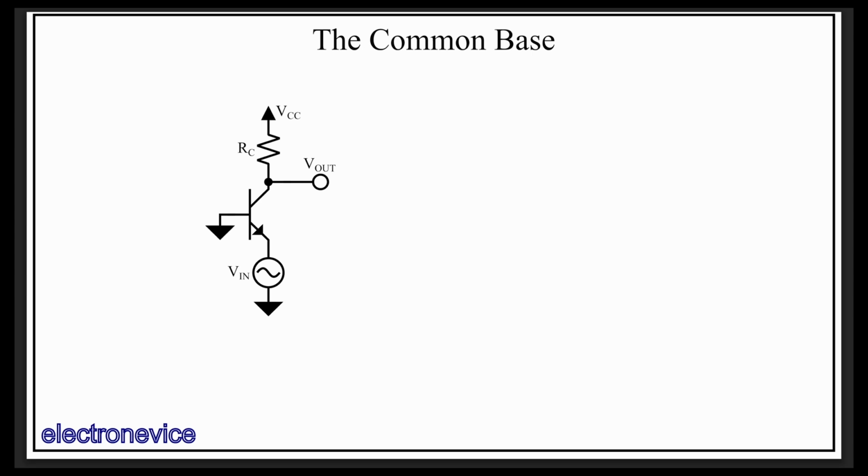We will, however, add two more resistors to this circuit to make it more realistic and thus make our derivation more useful. I've added a source resistance on the input voltage, as a zero source resistance is the ideal, and rarely are we blessed with an ideal circuit. The other resistance added is a resistance on the base to ground. Now you might wonder what the point of the resistor on the base is, as a simple piece of copper wire from the base to ground can be easily made to be extremely low resistance, much lower than an ohm. However, the resistor on the base is really there to represent resistance within the transistor base's semiconductor material and contacts, as these resistances within the transistor cannot be made nearly as conductive as a metal wire.